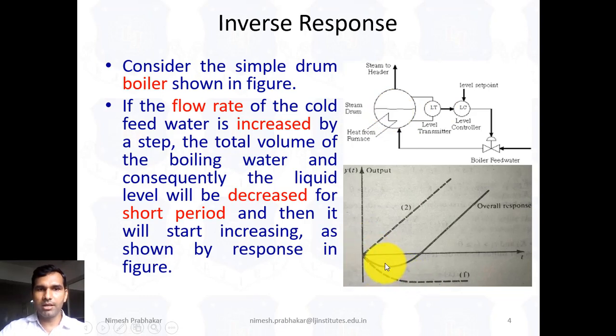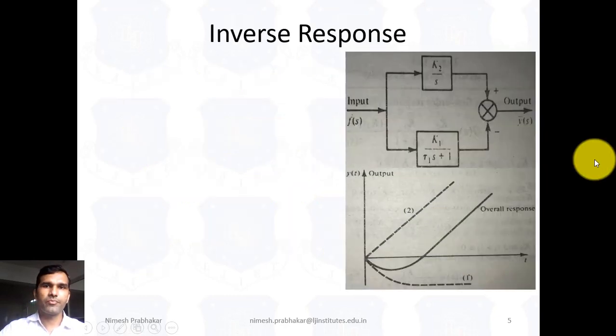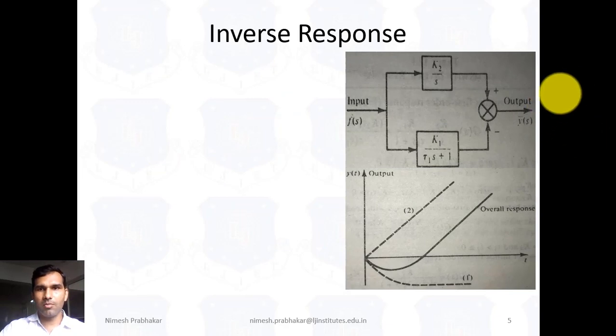The liquid level will decrease for a short period of time, and then when this inverse response effect is gone, it goes up to here. This is the overall response. This is the mathematical representation of this system.